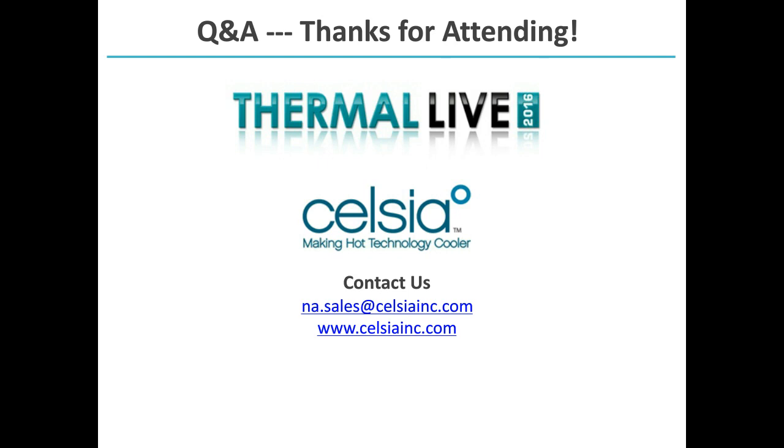Okay. Next up, a question from Jack at Elbit. George, what's the best solder material and process to attach the HP or VC to an aluminum metal sheet? Okay, the first thing you want to do is nickel plate the aluminum sheet, just because it makes the soldering a whole lot easier.